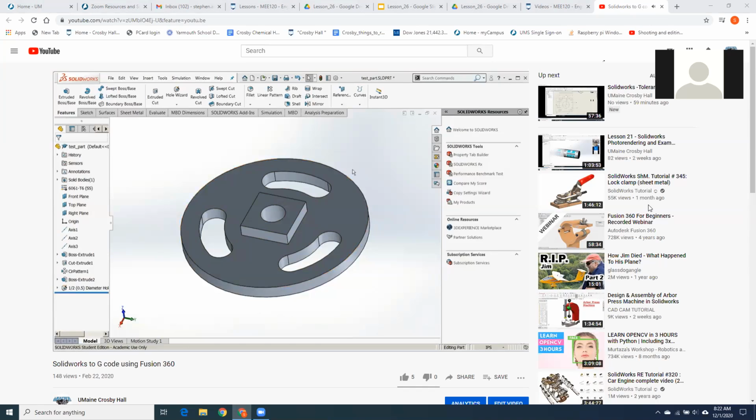Because I have mine properly aligned, we can go directly to the Step 203 exporting step. Step 203 is a file interchange format that was developed by NASA so that different CAD systems could talk to each other.